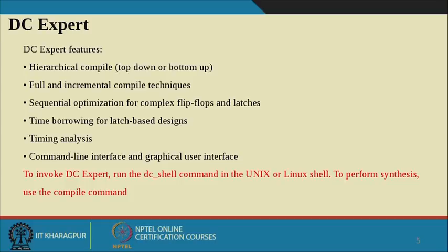Sequential optimization can also be achieved for complex flip-flop design or latch design. Time borrowing for latch based design can also be achieved. Better timing analysis can also be done through DC expert. And the best thing is that DC expert works in a command line interface, and a graphical user interface is also available, but mostly we prefer to use the command line interface.